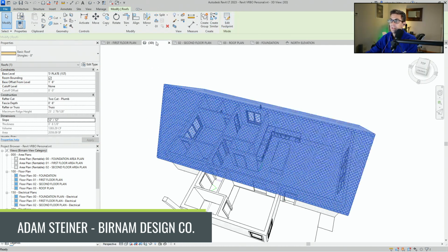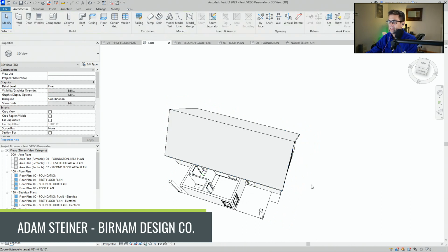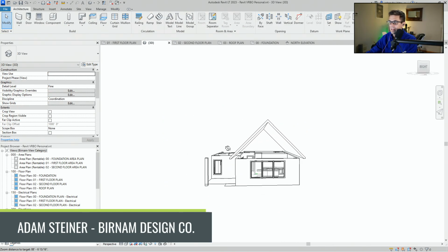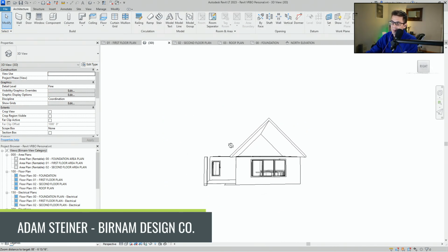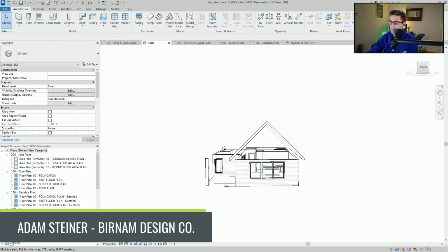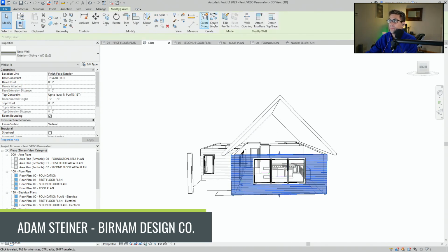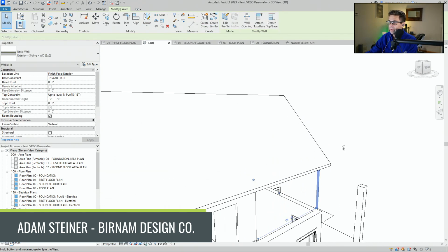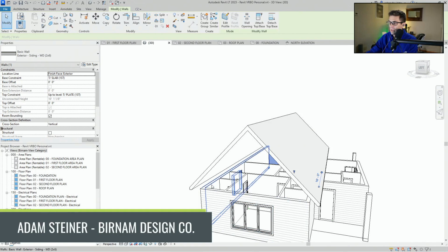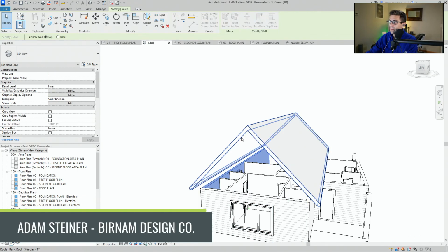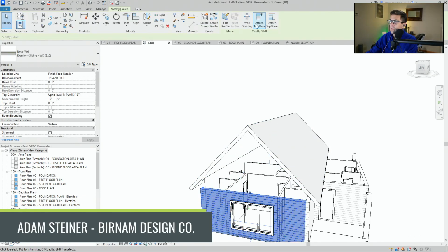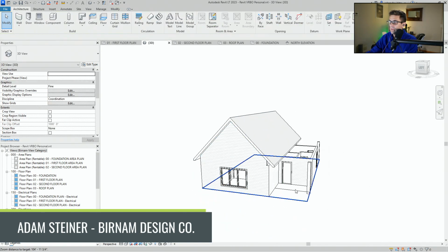Let's see here. Did I do it right? Hey, hey! Okay. I'm showing a massive heel because A, I want insulation, and B, with this being a slab on grade, I want to vault this area, so I need HVAC to run through that ceiling space. So I really want to make sure there's room there. So we're just going to attach top these walls to roof elements.